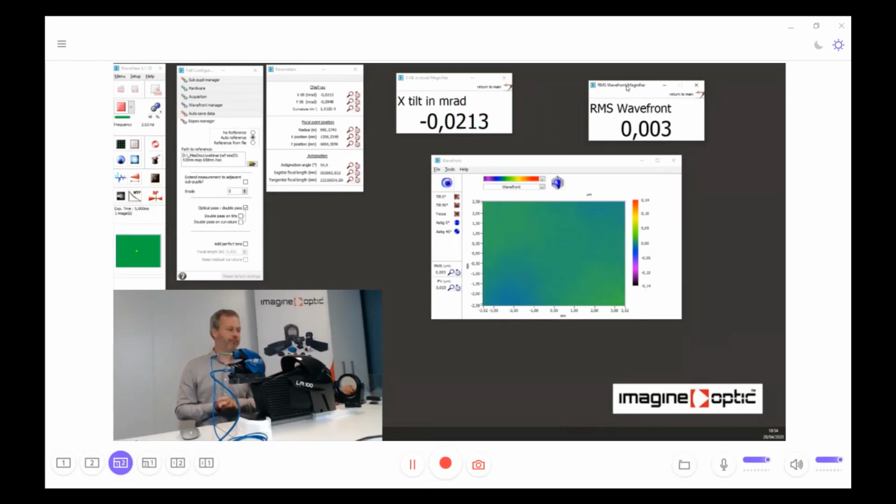It's important. I can show you something here. Now, I just create heat on my hand and put my hand here at the bottom of the beam, which has 100 millimeter diameter. As you see now, as the heat changes a bit the refractive index of air, we are able to see the influence of air turbulences in the room very easily. At the nanometers level of metrology, it's very easy to see the influence of air.